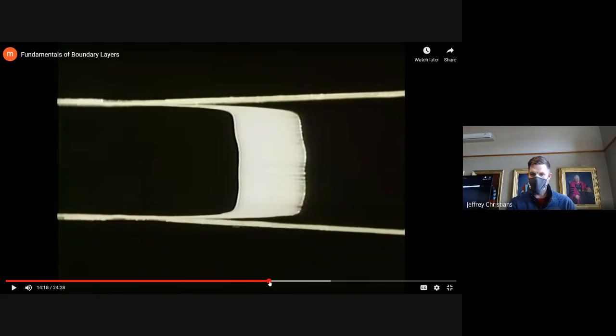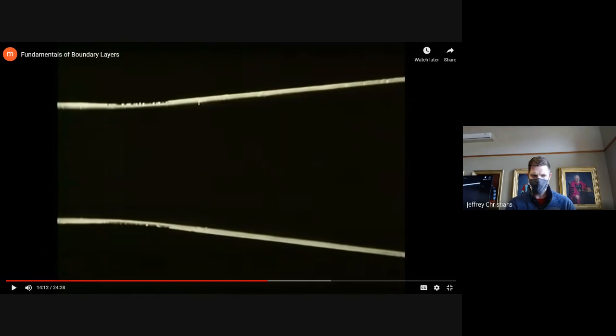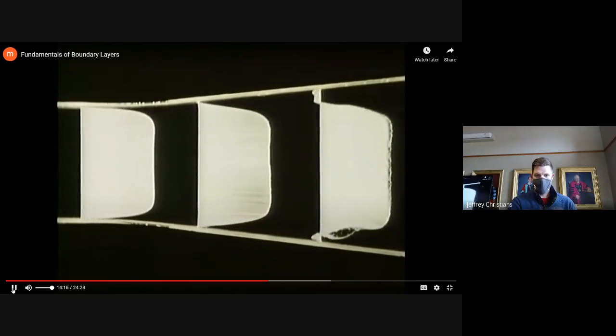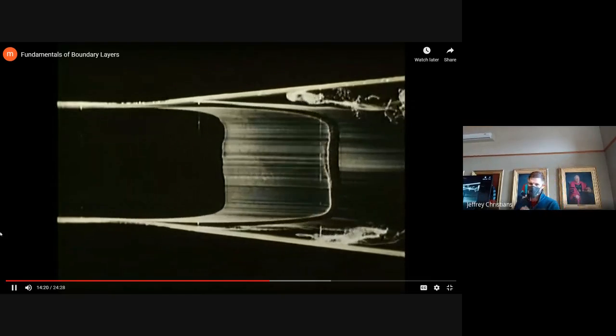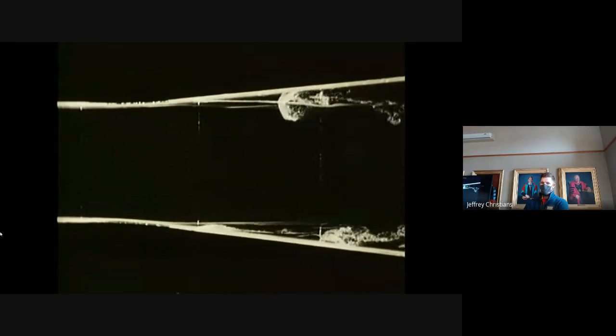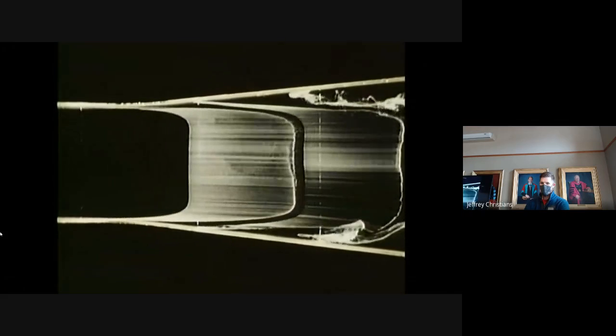When we go to a system like this, the pressure gradient is so much that viscosity can't keep dragging that slow fluid at the wall along, and pressure wins out and turns it around and pushes it the other way. Along the wall, the velocity gradient normal to the wall becomes zero, accompanied by a local reversed flow immediately downstream of the point. We call that boundary layer separation.